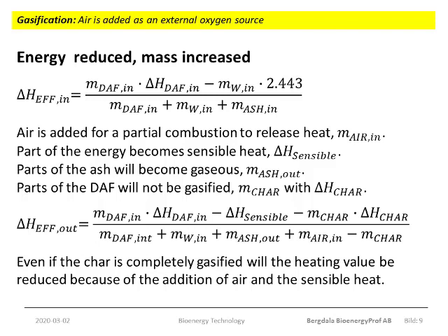The idea with gasification is to partly combust the combustible substance and also to change the solid residue, the char, into combustible gases. For this, there is a need for oxygen addition. Depending on the process, this can be done using air, and that is what I assume in this discussion. So the total mass of the product gas, supposing a perfect gasification, would be the incoming mass of the combustible substance, including the water, plus the total amount of air added.